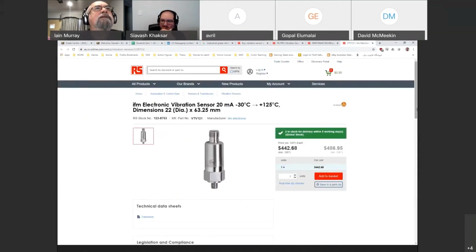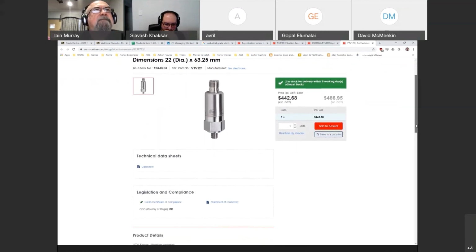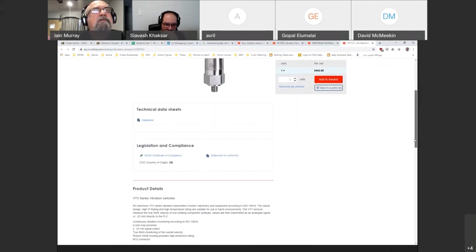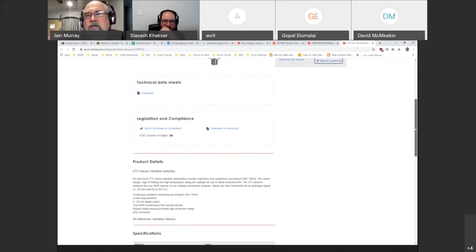Okay, so it's got a housing that can handle chemicals in case that is needed. It's completely enclosed. It has the right sort of fittings on it and has a reliability. So somewhere in there will be a mean time between failure. So that is a reliability measure. How long will it operate continuously before it's expected to break down? And that's a critical issue with